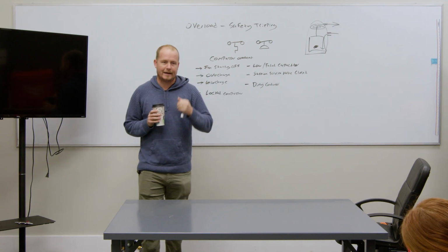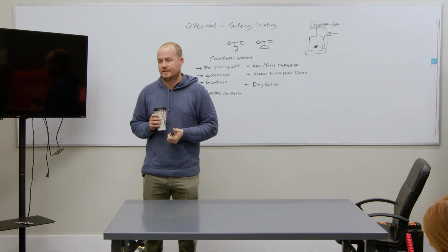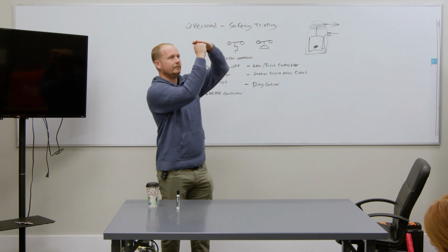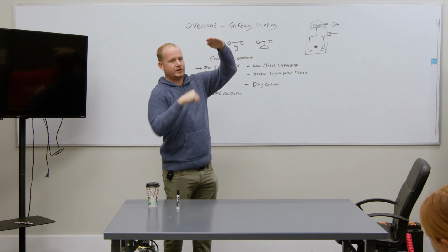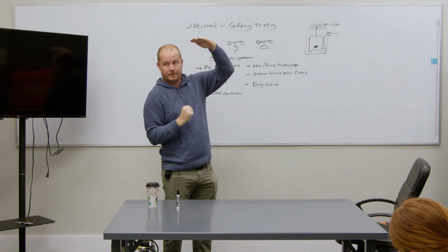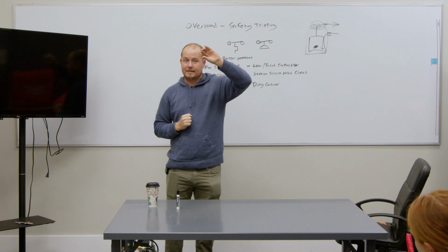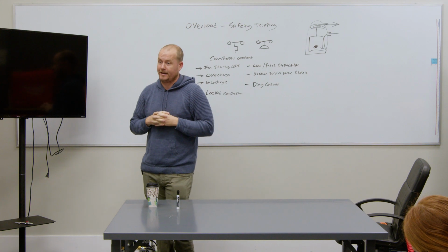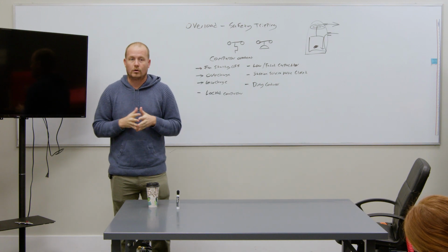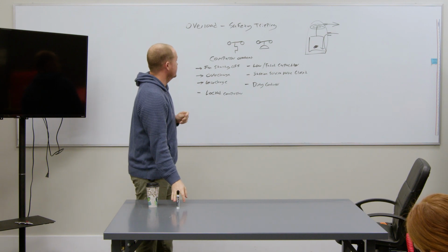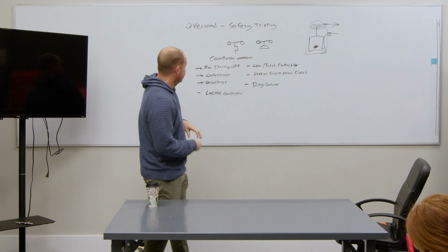And then depending on the design of that compressor, there's also going to be additional re-expansion inside the cylinders. If you have a reciprocating compressor, it's really easy to imagine this. It has to pull down far enough in order to pull suction gas in, and then as it pushes up, it discharges out. But there's always a little bit of refrigerant left in the top of that head when it takes the downstroke again. And so if that is really high pressure, really high temperature gas, that's going to run hotter because now you're re-expanding that higher pressure, higher temperature gas back into the compressor again. Versus a scroll or rotary compressor where it's continuous compression. So there are some variances in that depending on the technology. All right. Any questions about that?